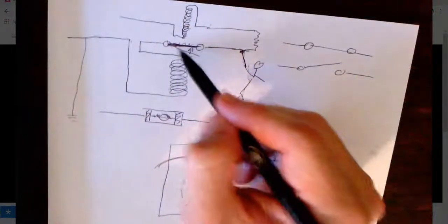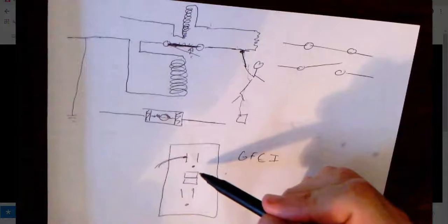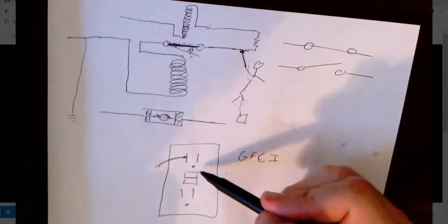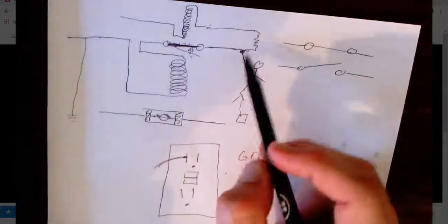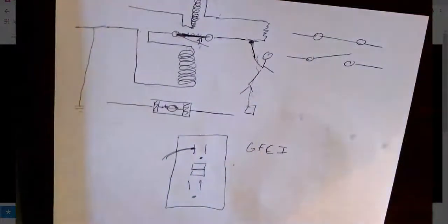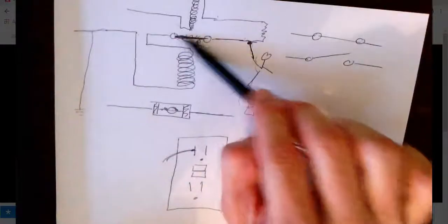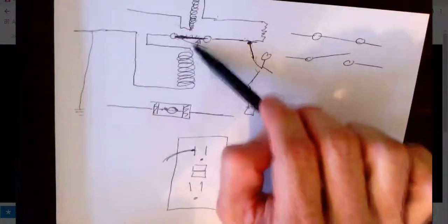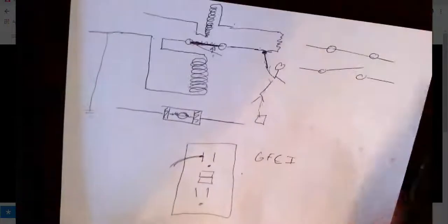And this is much more local. It's very close to this, and it's supposed to shut off the circuit fast if you start getting electrocuted, because it's close in the line, and it doesn't have to have a huge amount of current for it still to trip this. Imagine there's no spring in this. It's just very easy to move. If these currents are different, then it's going to open that and hopefully save you.